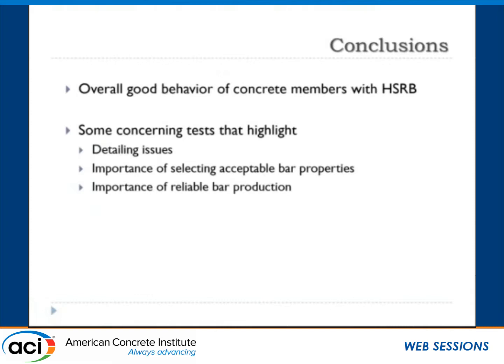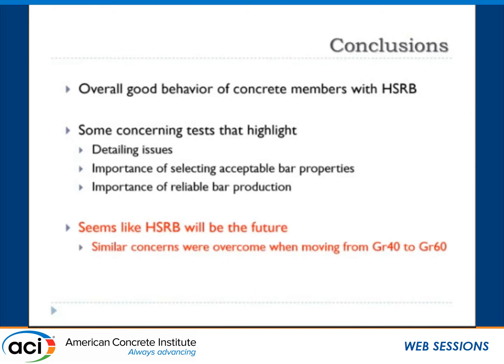Overall, very good behavior of concrete members with high-strength reinforcing bars. We've seen it in beams, in columns, and in walls. We can get good performance. Some concerns have highlighted detailing issues that we need to iron out. We need to iron out acceptable bar properties and make sure that production is reliable and repeatable. And in the end, in my humble opinion, I think high-strength reinforcing bars will be the future. I think they've shown that they can do the job, and do it well.